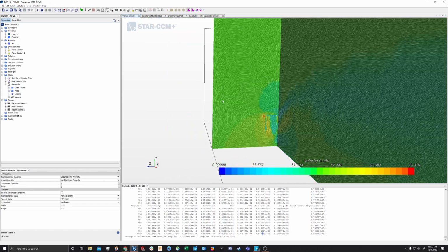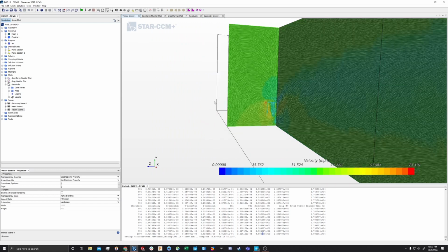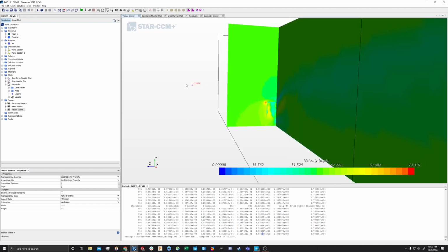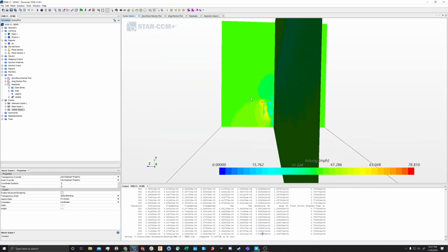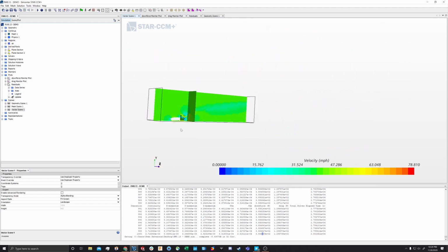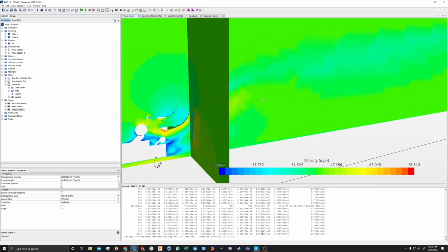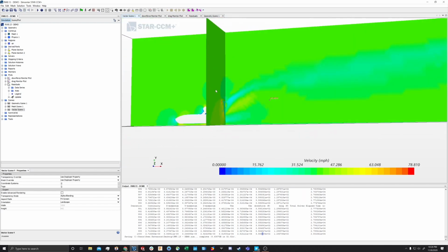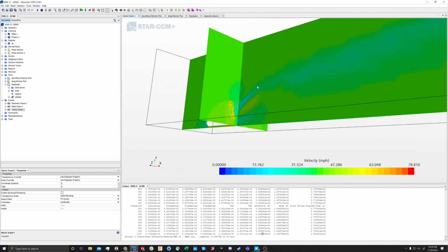And then you can also see these vortices propagate out. And clearly there's not enough space within the block for them to really hit their full size. You can see they're kind of running up against the walls here, so that could be part of the reason why this sim did not quite converge as well as we might have wanted. But yeah, that's a good analysis tool. I like to use that one a lot.